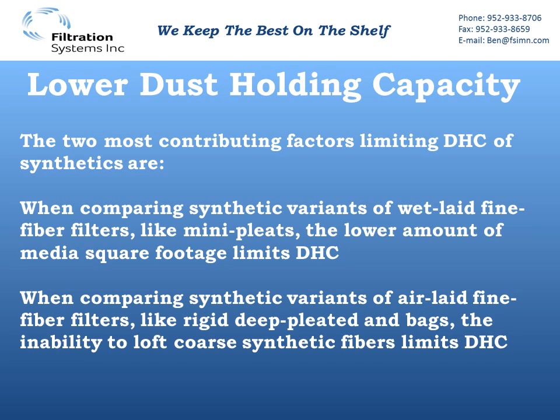When we look at synthetic variants of air-laid fine fiber filters, the square foot per filter of media is going to be about the same. However, the fine fiber filters, like the rigid deep pleateds and bag filters, have a very highly lofted media, and this loft adds depth to the filter media, which will give you a very, very high amount of depth loading in the filter.